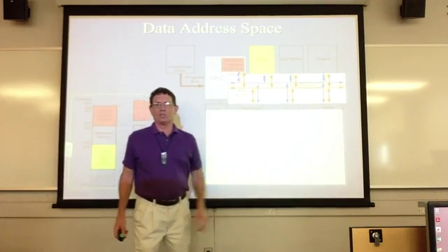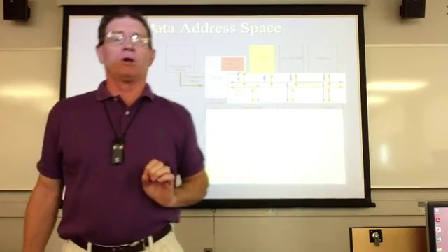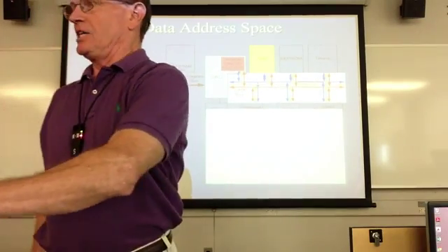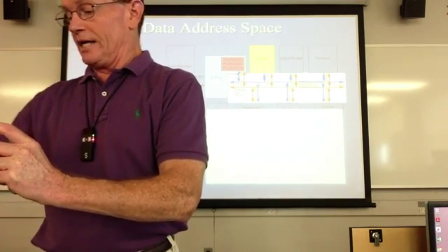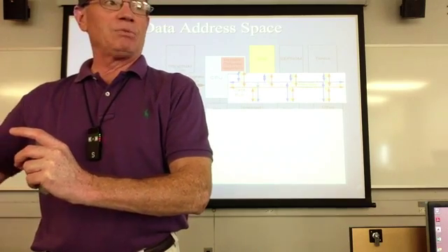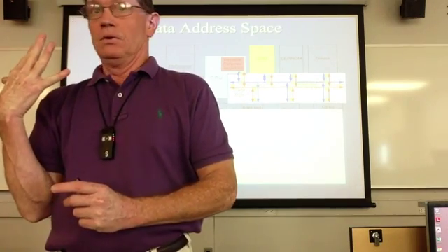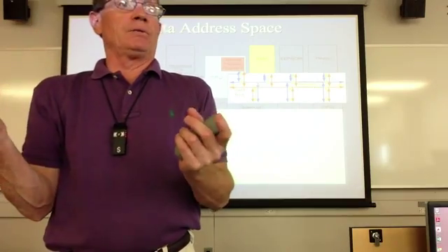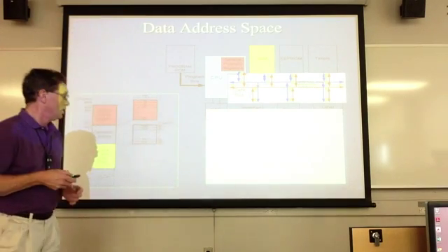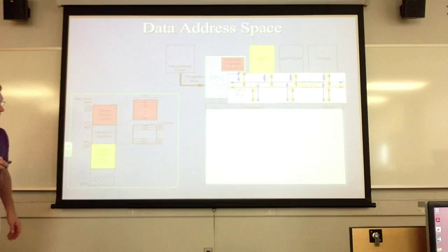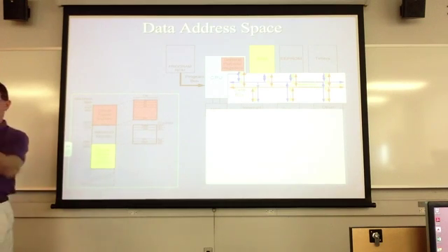What this does: on your Butterfly board, if port B has some inputs to it, like a little voltage and some dip switches, you can actually set them to be inputs. So I can read in data coming in. You can think of it as door alarms or something. They're all just going to be attached to a set of I/O pins on an I/O port. And then the IN command is I just take a register that's going to accept the 8 bits in, and then I give it the address of where that is.